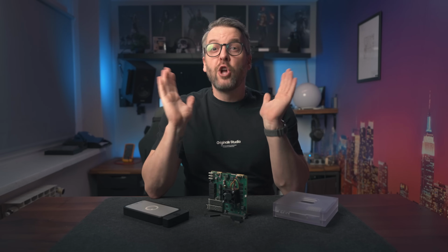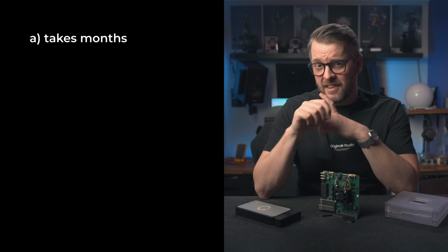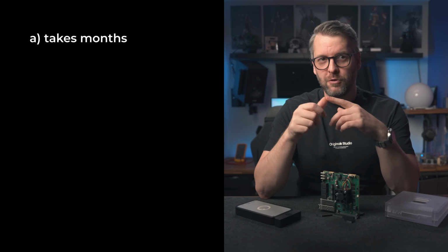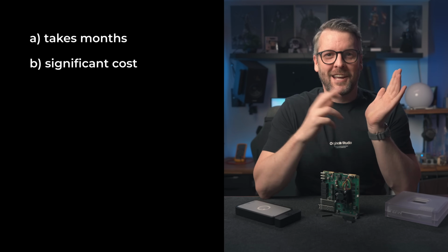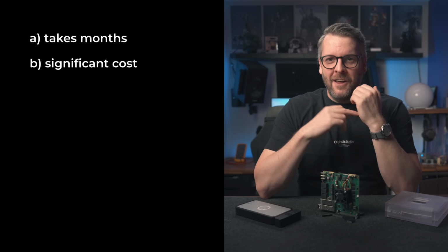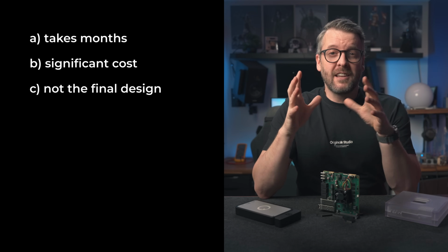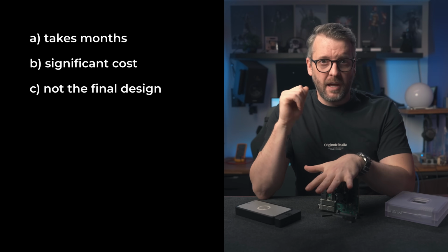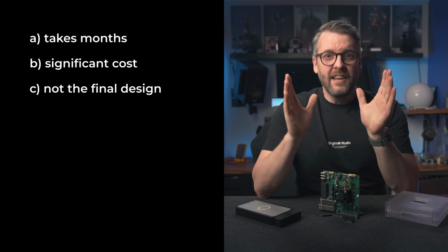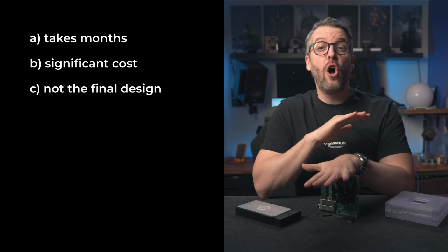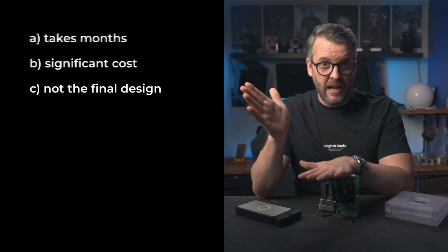Now, keep in mind we don't plan to officially certify our development kits because A, it takes much more than a day to do it officially, B, it costs way more than just a plane ticket to the Netherlands, and C, which is what I'd argue is also the most important argument, the development kit is not a final version of the PCB. And if you make any changes to the PCB, and I do mean any, then you have to recertify it all over again, even if it's just a value of a single resistor.